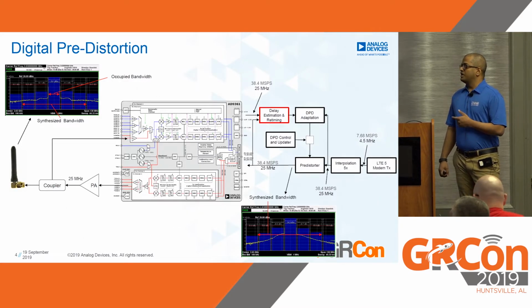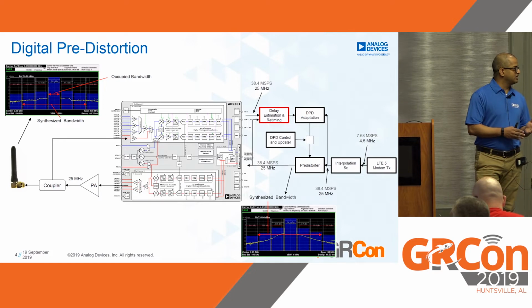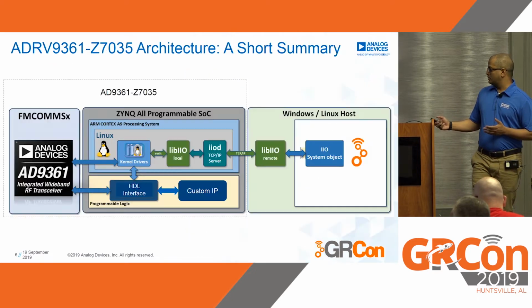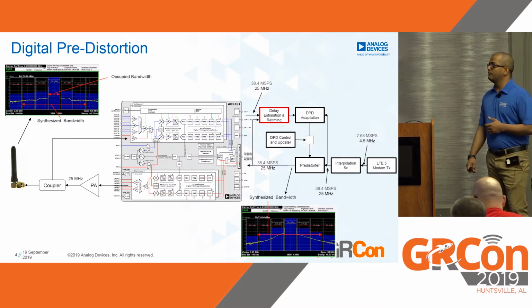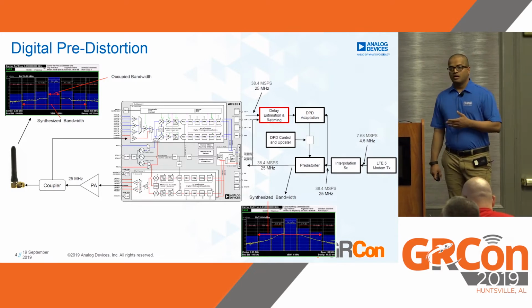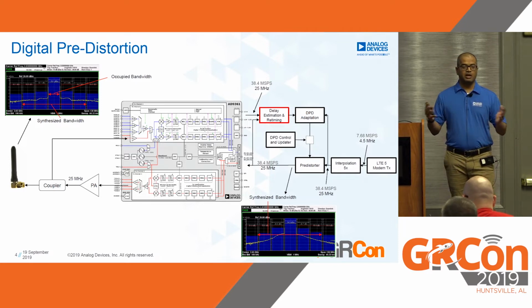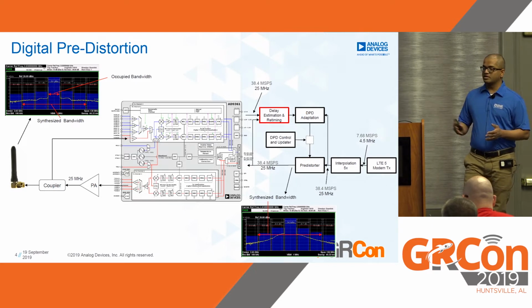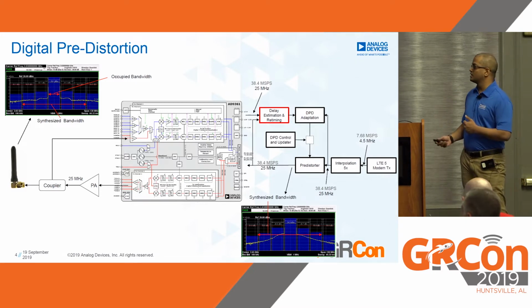To go into a little bit of detail concerning digital predistortion and where loopback timing delay fits in this context, if we think of the transmit waveform as, let's say, the LTE compliant waveform, its bandwidth is going to be 4.5 megahertz, and the mandated sample rate is 7.68 mega samples per second. But typically, we want to oversample this signal because in the context of digital predistortion, we want to look at the ACLR values in the first adjacent channel on either side and second adjacent channel on either side. So that requires that you oversample the signal 5 times.